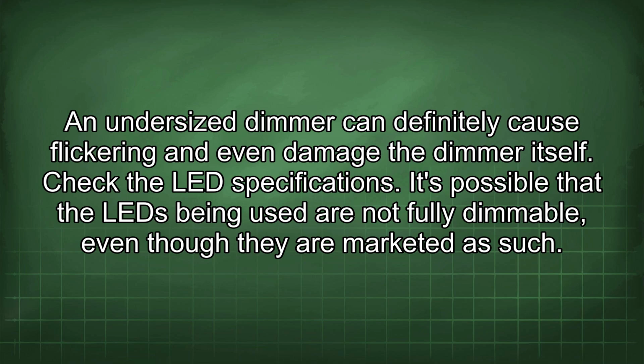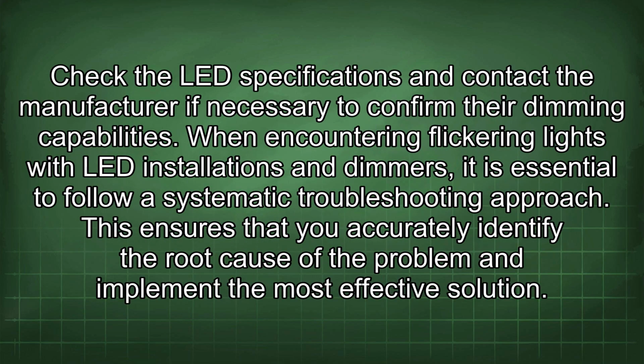Check the LED specifications. It's possible that the LEDs being used are not fully dimmable, even though they are marketed as such. Check the LED specifications and contact the manufacturer if necessary to confirm their dimming capabilities.